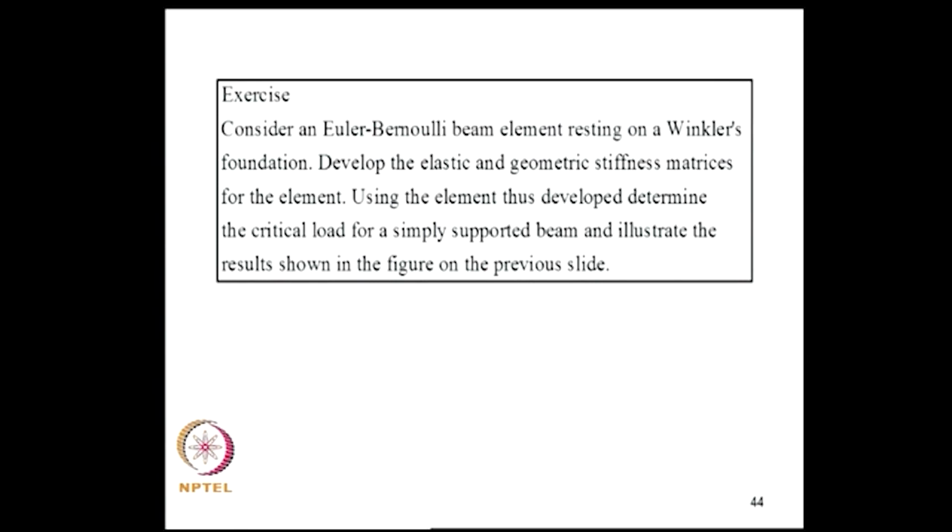So now as an exercise, we could consider an Euler-Bernoulli beam element resting on a Winkler's foundation, and you can develop the elastic and geometric stiffness matrices for the element. Now using the element thus developed, determine the critical load for a simply supported beam and illustrate the results shown in the figure on the previous slide.